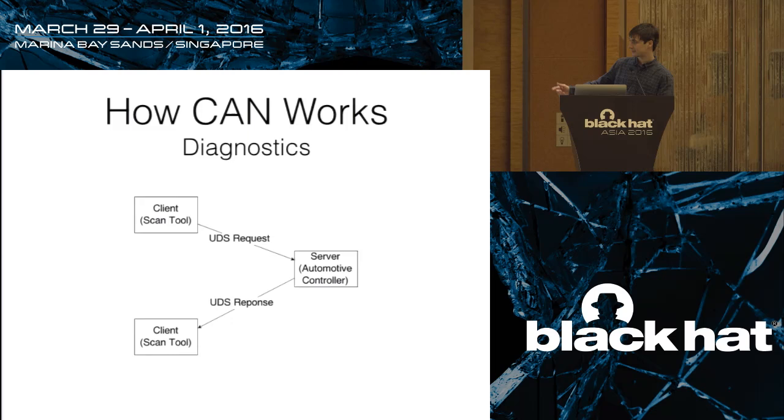So you typically see this as a scan tool, which is what a mechanic is going to be using plugged into your vehicle over the OBD port in the car. It's going to send out a request. That server, which is the actual controller, generates a response and sends it back. And you can chain these together to create sessions. There are different ways of implementing security for the sessions and all that, but this is the other common application of CAN other than just signal databases.